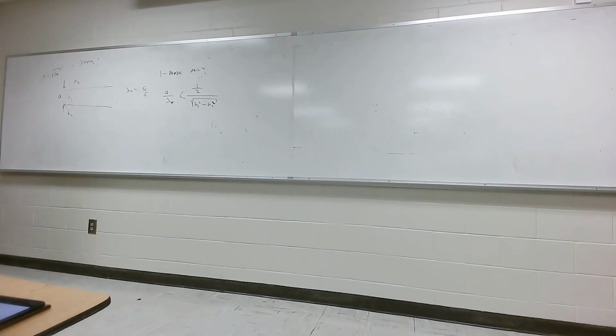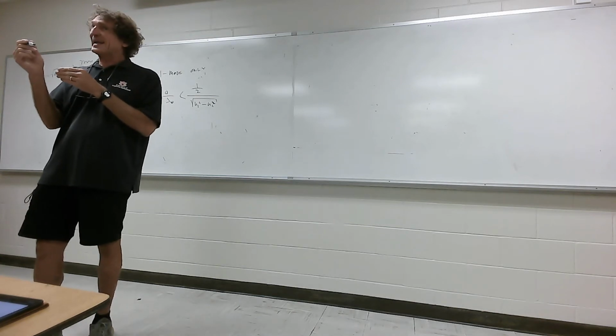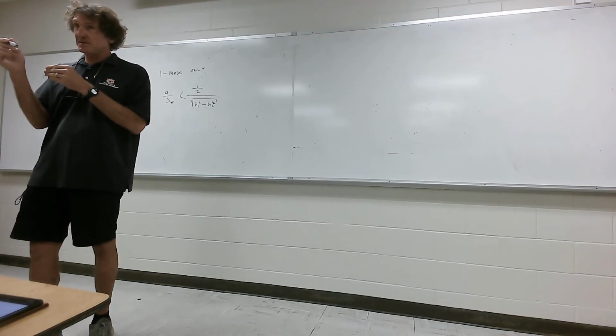Now, any frequency below that will only propagate a single mode. Why is a single mode important anyway? Why don't you want 2 modes or 3 modes? Because you will have power split in the modes and it'll propagate at a different velocity. Y'all follow me in this class?